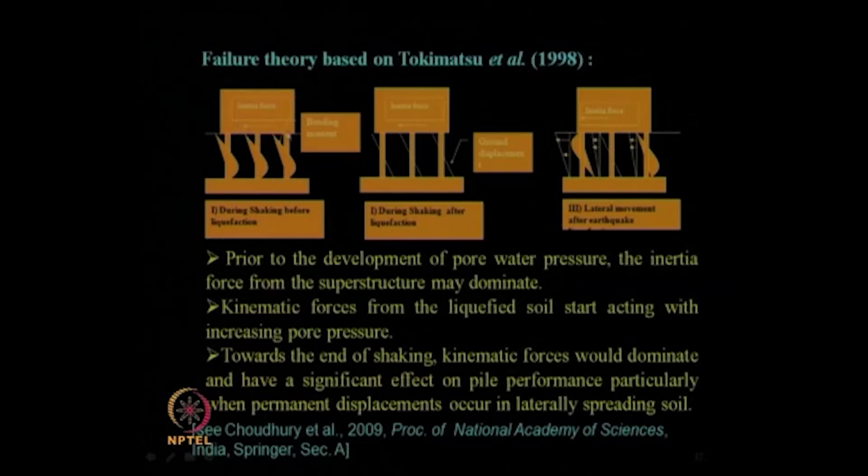If you see, this is your superstructure which is constructed on pile. Now, during shaking, before your soil gets liquefied, when just the earthquake came, inertia force is acting, right. So, pile is getting extra bending moment because of extra lateral load. Now, during shaking, after liquefaction, when the soil gets liquefied, there will be a displacement of the soil also. So, inertia force will still act and the soil gets displaced.